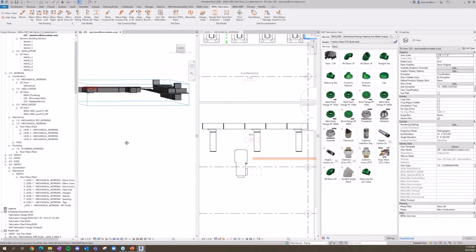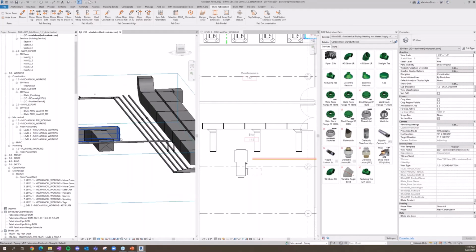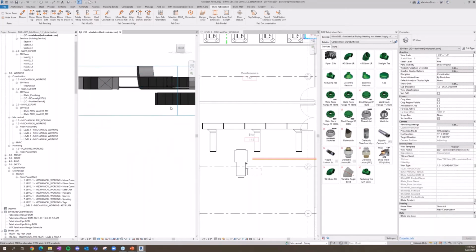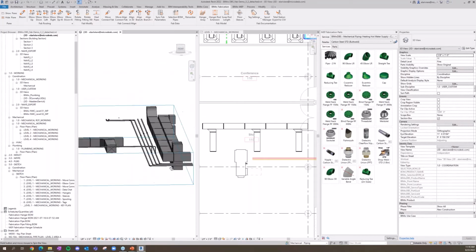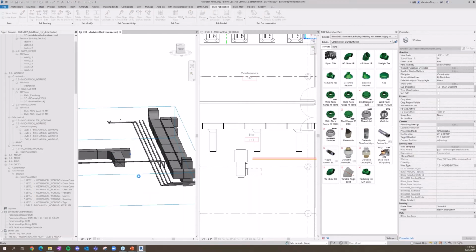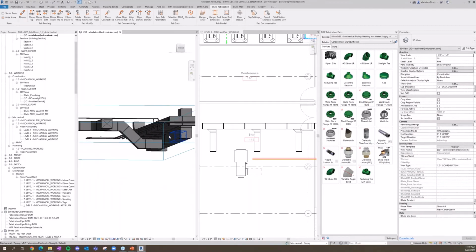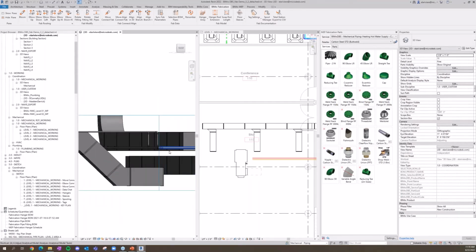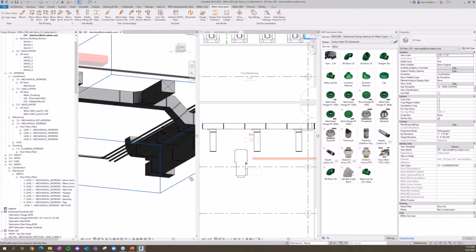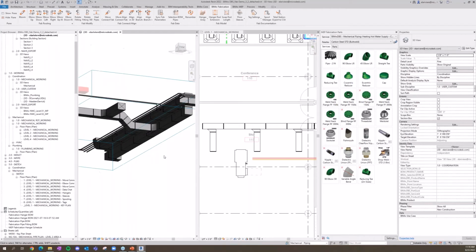Now, if we take a look, I probably need that duct to route and connect to something. If I go straight though, I'm going to be going through that pipe. So my guess is I'm probably bringing that down to my lower element. So sure, cut some section views and do that, or elbow 45 down to give myself that down run. Elbow 45 up to bring myself to a level off. Look underneath, get close, use align branch. Line our elements up, use trim extend to bring them back together for that final connection. Very, very quick to model.